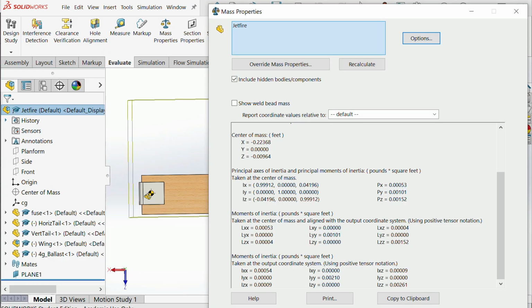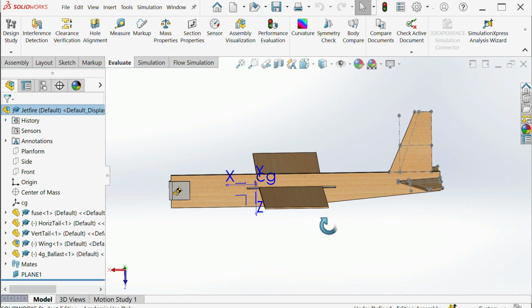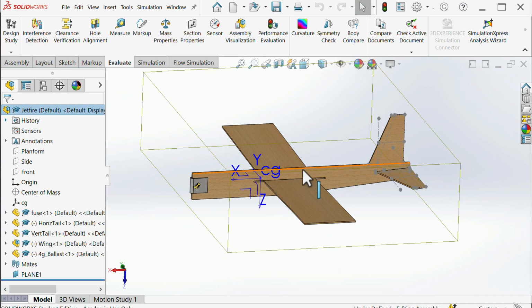So you just go back to the basic aerodynamics. Maybe there are a lot of different parameters you can change, right? Let's go back, and if we look at the airplane again, just think of some of the key things you could change, even on this glider, without changing anything in terms of its overall design. Like, you could keep the wing the same, and just moving the CG around would allow you to trim at a different airspeed, which may be more optimum for this airframe if you're trying to do endurance.